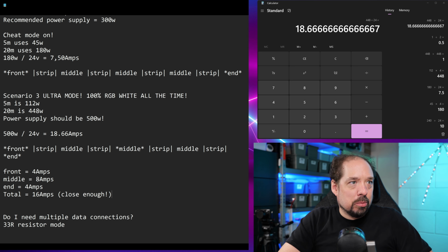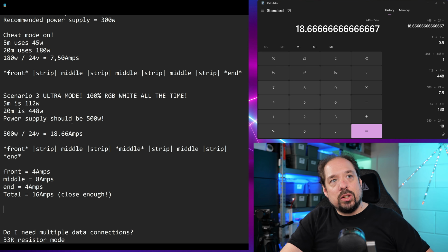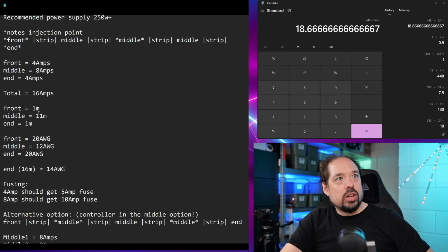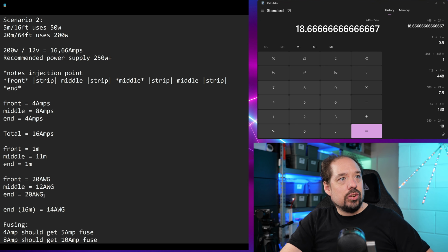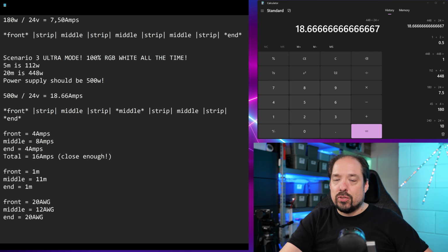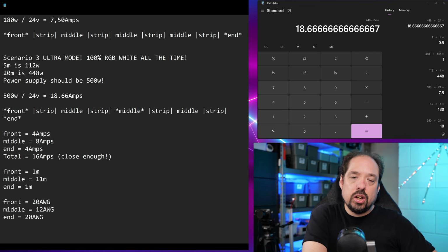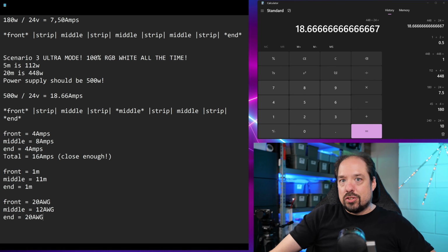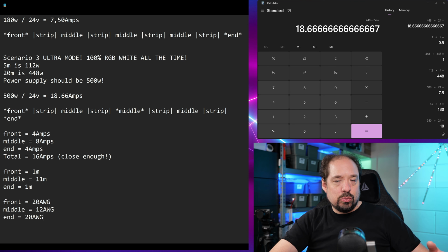There's always a little bit of margin there. But that also means we already know what kind of cables we need for that, because, well, this scenario basically just applies. It's the same calculations. It doesn't matter if it's 5 volt, 12 volt, or 24 volt. Calculating amps is amps. And that cable can carry that much amps with so much voltage drop.